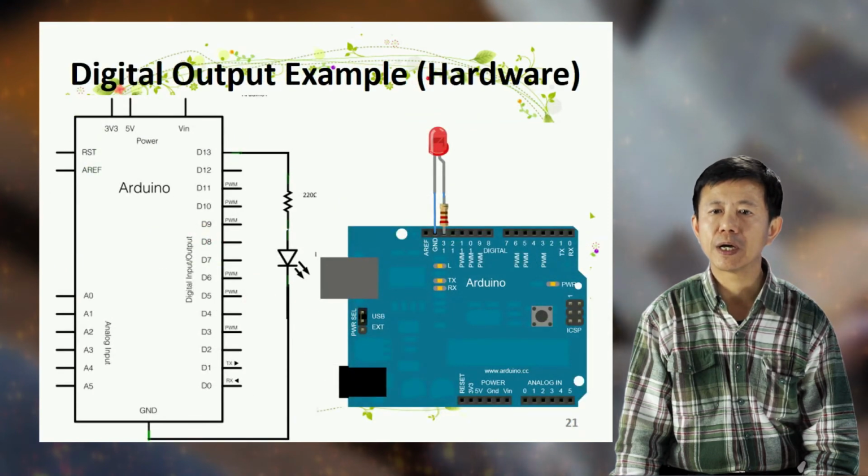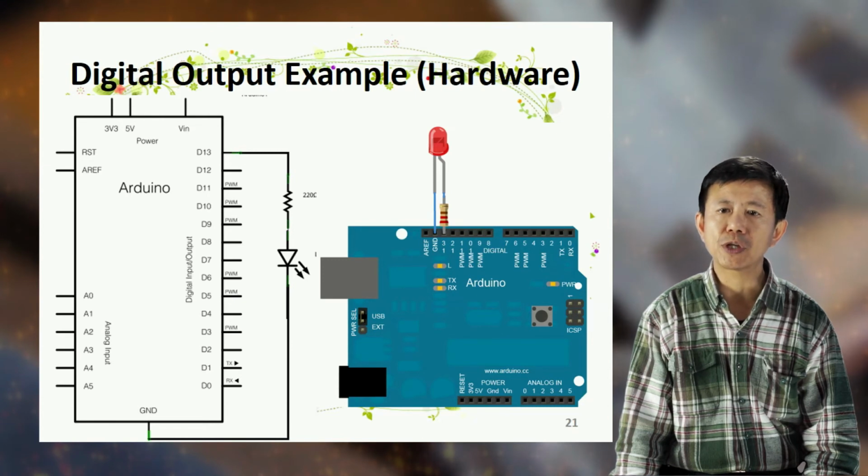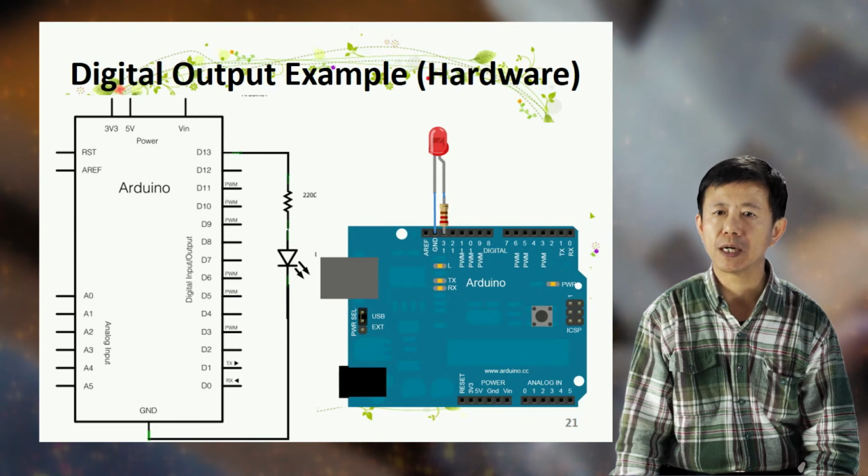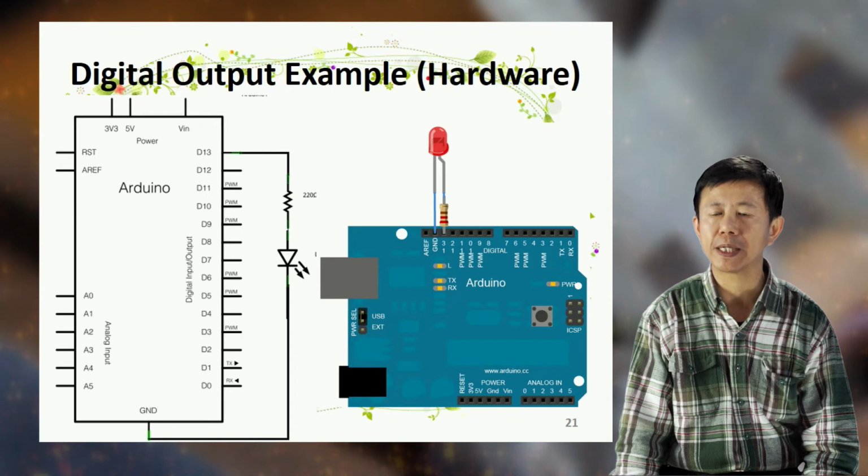In step 2, LED on using Arduino's digital output. Digital I/O pin 13 is chosen. Hence, in the hardware part, the schematic and layout show that instead of the 5V power pin on the Arduino board, the resistor now is connected to the digital I/O pin 13.